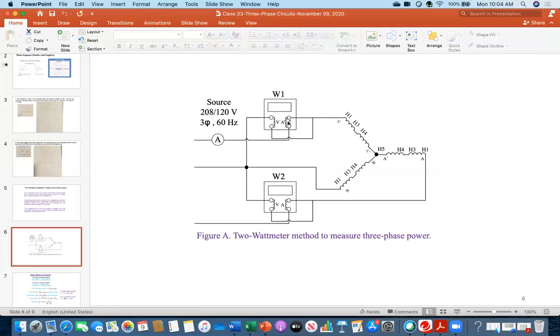So this is a coil, because a wattmeter, meaning that it will measure the power, which is the multiplication of voltage and current, even without that power factor. So that's why there are 2 coils, voltage coil and current coil. And then you see how the current coil is connected. You see it is connected, for example, in series, because it will measure the current, and always an ammeter is connected in series.